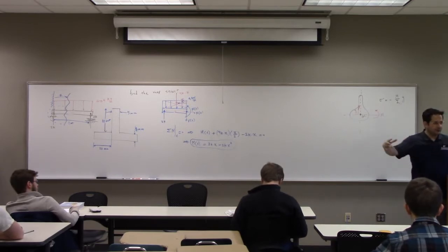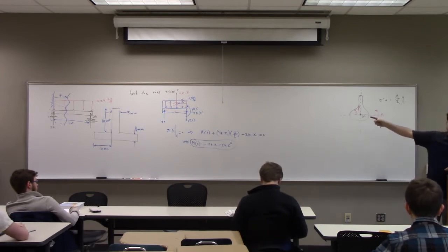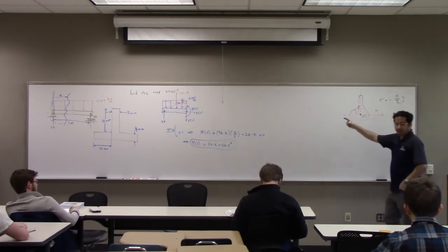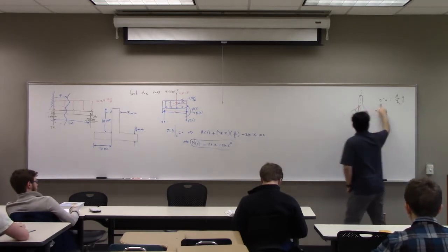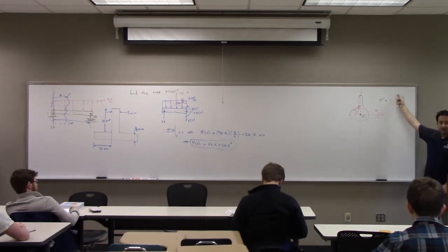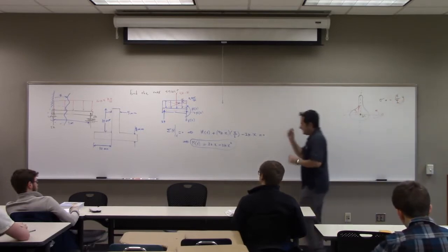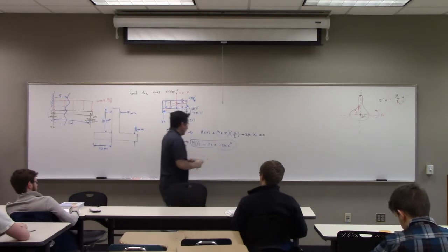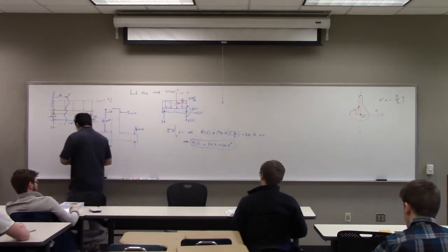That means the entire field, the stress. But right now, I'm not asking for the stress field. I'm asking for just a particular point where you have maximum stress. So you come here and say this is maximum when the moment is maximum and the y is also maximum, right? So you should consider all different things to get the maximum. So if I draw that, how many points do I need? Let's draw it here.